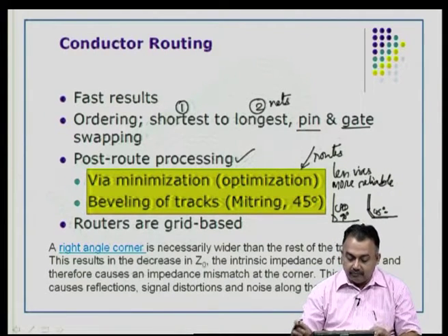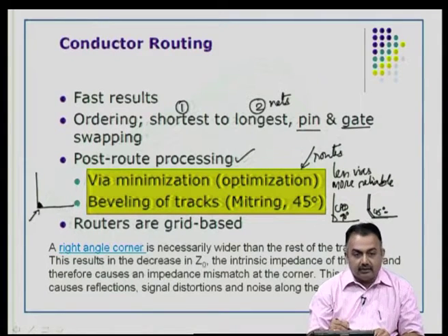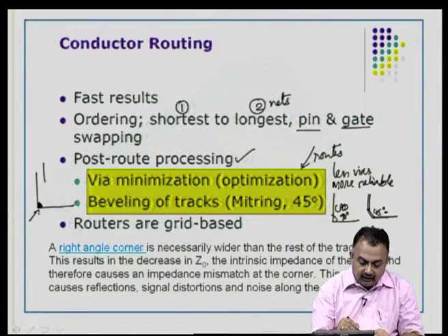And from the manufacturing point of view, if you look at a right angle like this, in processes like imaging and etching and so on, which you are going to see, this corner will be a major problem. This can chip off if the process control in processes like etching are not well maintained, and you also gain more area when you convert from 90 to 45, because if you want to run bus conductors like this for digital signals, you will get more area.